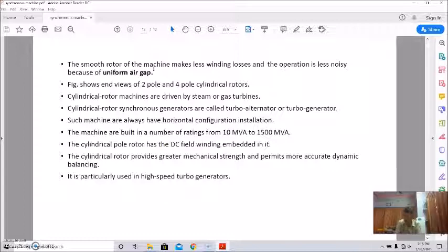The rotating field is comparatively light and can be constructed for high speed rotation. The armatures of large alternators are force cooled with circulating gas or liquids, and since the armature winding is on the outer portion of the machine, cooling can be done easily.